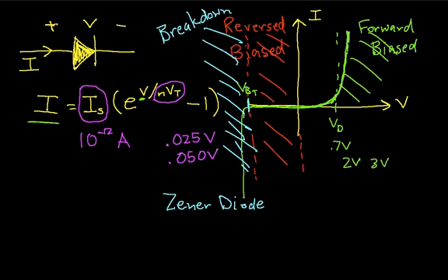VI curve, because it turns out that most of the time you don't want to deal with the Shockley diode equation directly. The only time where this equation turns out to be an important model is when you are using a diode to build, say, a logarithmic or an exponential amplifier with, say, an op-amp. And that's really beyond the scope of what we're talking about today. So you typically don't want to use the Shockley diode equation directly. And what we do is we come up with a couple of approximations, depending on what we're looking at, for the VI curve for the diode.